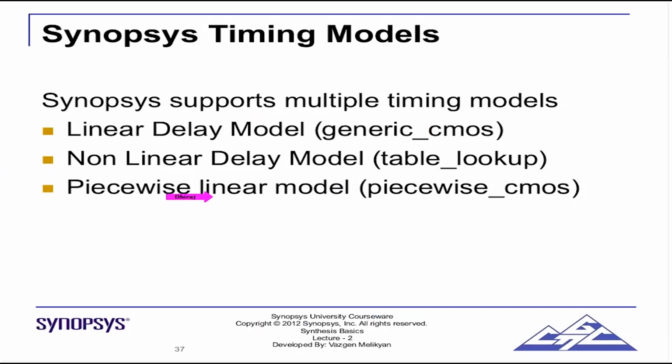Now, the first one, linear delay model, is a very basic, simple model, and that is why it is not used for present day technology. But we'll go over this. We'll lay some foundation here. The non-linear delay model, in short NLDM, was the most popular choice of model till 3 or 4 years back. In fact, your Synopsys 90 nm generic library will have NLDM. So we look at this in detail.